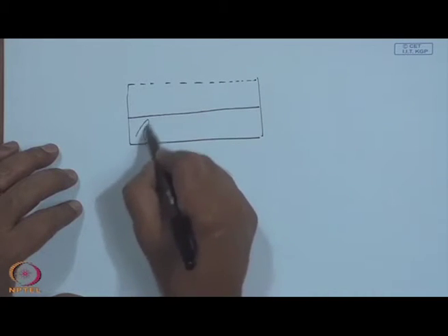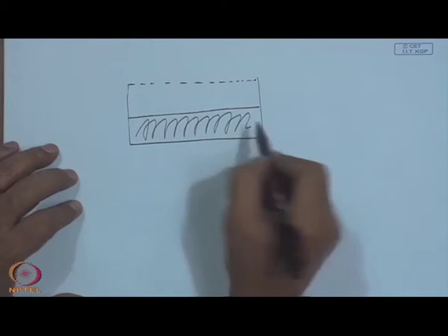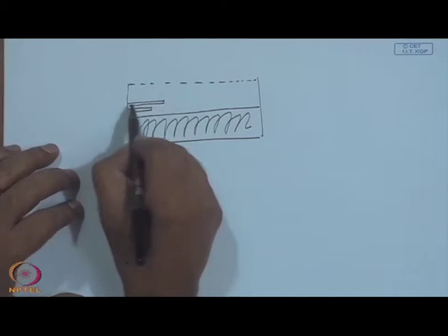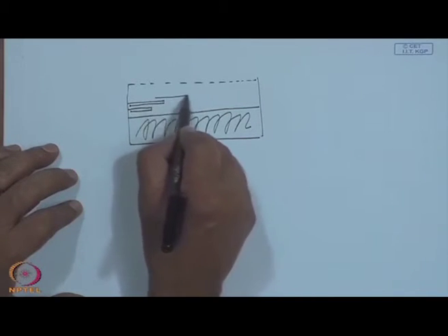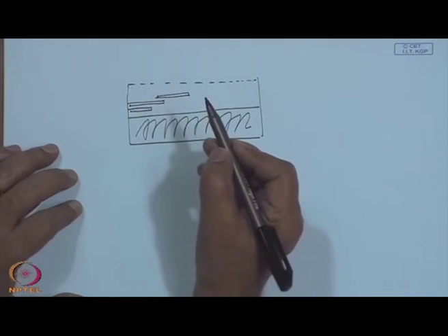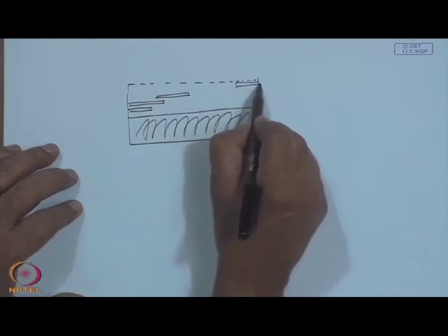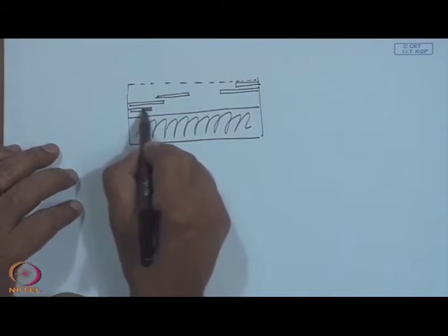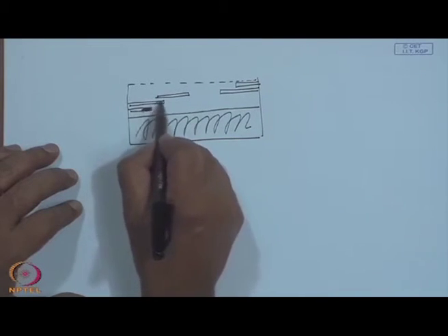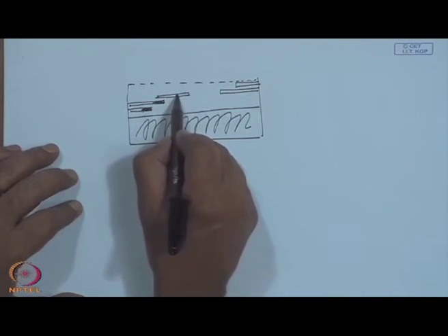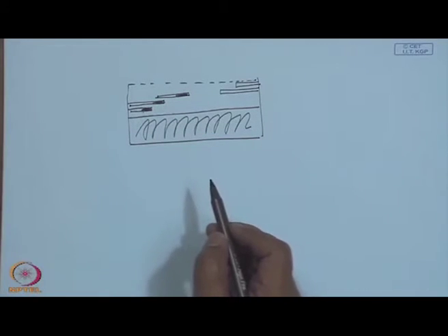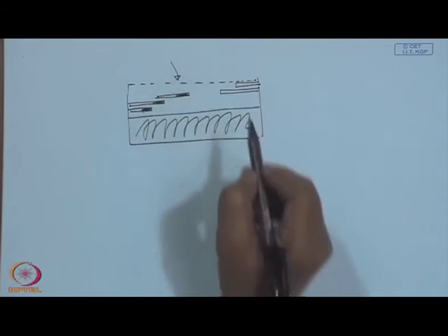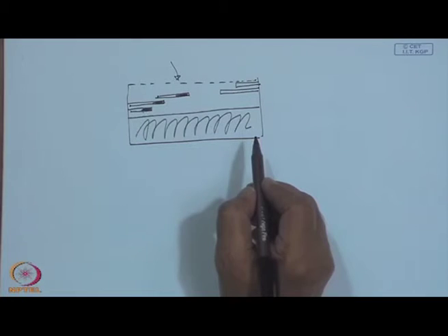This bottom is insulated, and you have got plates, then another here, like this, up to here again last, then this may protrude a little more with a black painted portion and a transparent portion, one overlapping the other, so that the transparent portions will be transmitting the solar radiation falling on the top surface, whereas the black one will be absorbing the solar radiation.